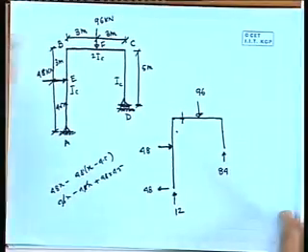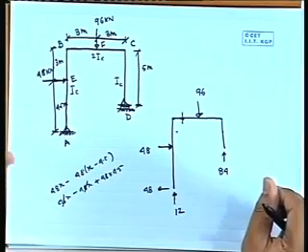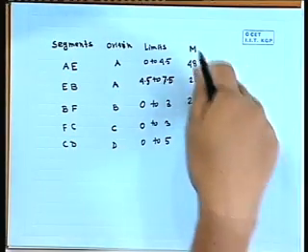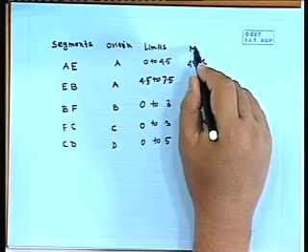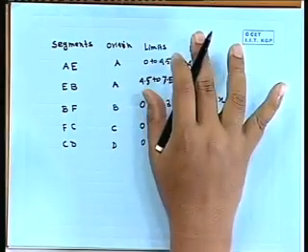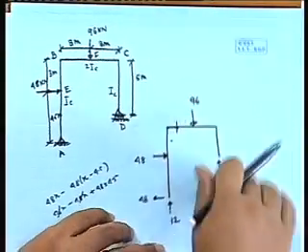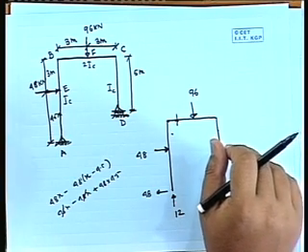Now in unit load, we have mentioned that we can find out the deflection or slope at any point with the formula integral of capital M, small m, dx divided by EI, over the different segments. Now this moment expression we are defining as capital M. So it is due to your applied load. These are the loads acting on that. This will be the actual moment generated in the structure.